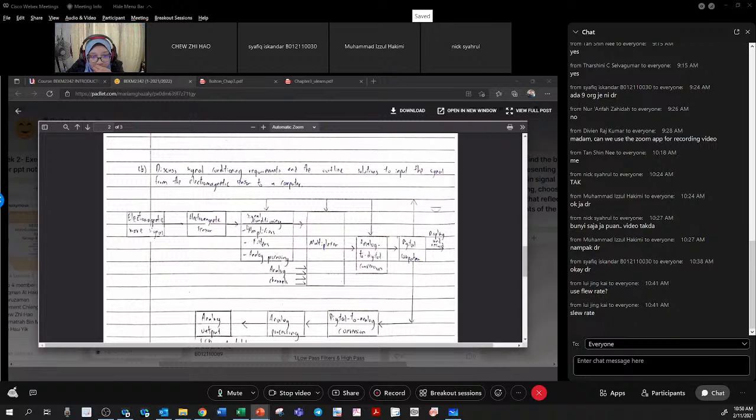After that, it is passed to the signal conditioning, which is amplifier, filter, and analog processing. So that it passes through the multiplexer, which collects all the analog, then does the analog to digital conversion, to allow the computer to read and display on the screen.